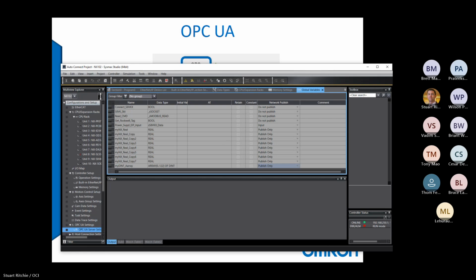Okay, perfect, yeah. And you may have noticed, or you may recall that this power supply Ethernet IP variable that we made is actually a structure. And the UA client detected that. So we can, and I'm not going to say every client can deal with structures properly, but a lot of the popular SCADA offerings can deal with structures directly. So yeah, we can save a lot of data mapping in some cases by dealing with the structures directly, right from the input variable as well. Perfect, thank you. Yep. Any other questions on OPC UA?